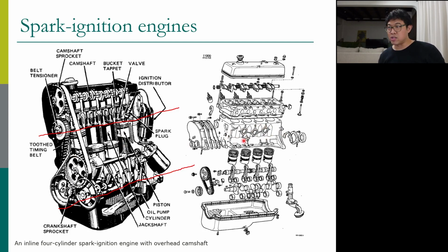For four-cylinder engines, you have cylinders, which are basically the hollow core inside. And you have pistons installed inside the cylinders because they have to move inside the cylinder, right? So these are different parts. The piston connects to the connecting rod and connects to the crankshaft. This is a picture of a crankshaft. On top there is the cylinder head, like a solid block with these valve trains inside the block. And then we have the valve cover on the top. So that's how engines look.